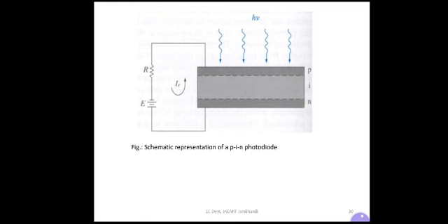But the disadvantage is that a large W leads to a very sensitive device with a low RC time constant, and if the drift time is excessive, this again leads to low speed. So we have to compromise between these two, that is a trade-off. The appropriate width for W is chosen as a compromise between the sensitivity and speed of response.